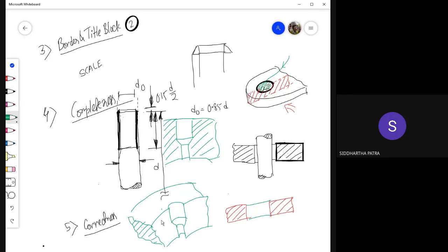Okay, so if you're looking at this section from the front view, you should also be seeing all those circular arcs which are part of cylindrical surfaces as straight lines, and all the cylindrical surfaces as rectangles. Okay, and this conical surface in the middle, between two cylinders there is a conical surface in the middle, that you would be seeing like a trapezoid.